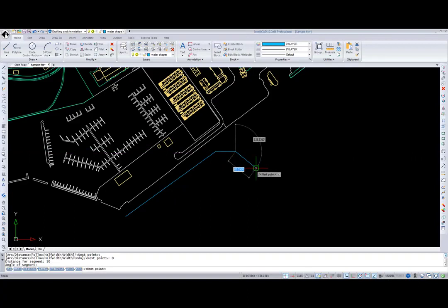Let's say I want to draw using a specific angle. So I use the tab key to navigate to the angle edit box and type 30. Switch into the previous box and see that value 30 is locked. It's like being in polar tracking mode, but you're not limited with the angle value.